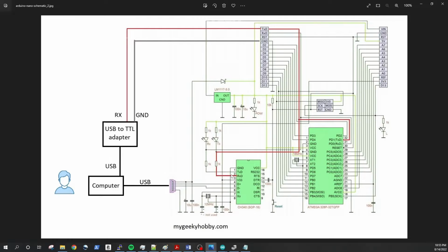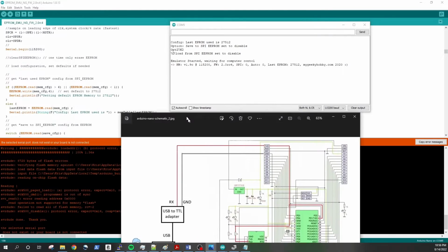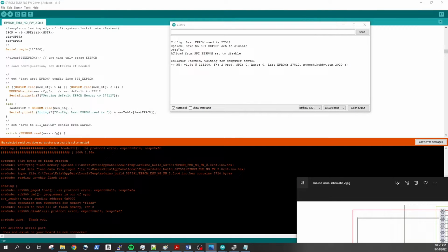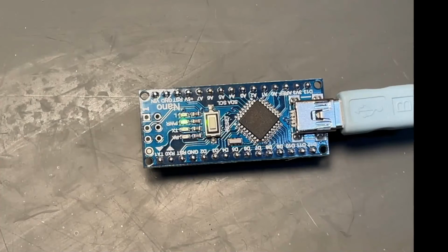Well, what we can do is attach to our computer a secondary USB to TTL adapter and hook ourselves into the same signal out of the processor and look at both of them and compare: are we seeing the same issue on both or not? This will confirm that it's actually the CH340 converter chip that is the culprit here, and that's what's breaking the communication. So let's do exactly that. Let me take you to the desk.